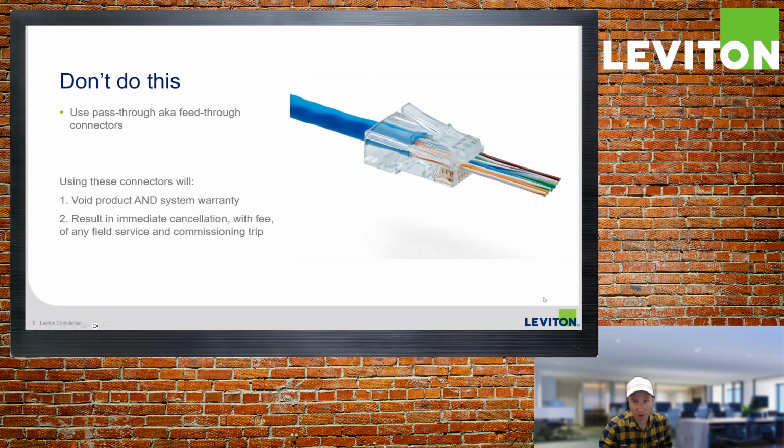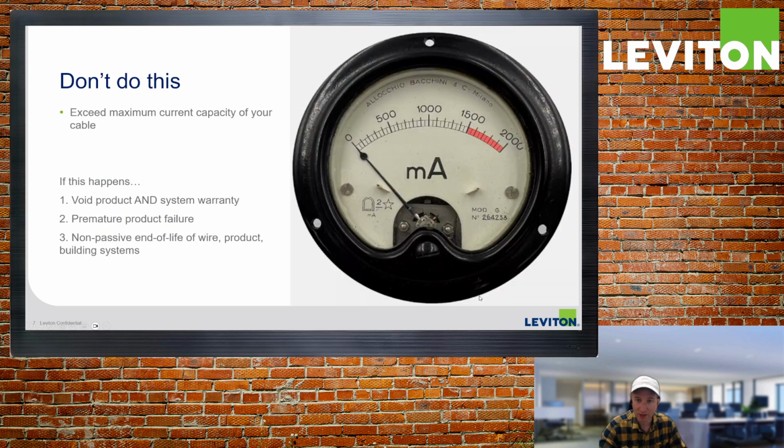Second thing on the don't do list, do not use pass-through, or some people call them feed-through connectors. Those are the connectors where you push the wire all the way through them and then snip them off at the end to get a connector. We do not support them on our systems. If we find them, it will void the product and system warranty. We will also walk off the job site until they are replaced. We cannot guarantee a reliable system if you use pass-through connectors.